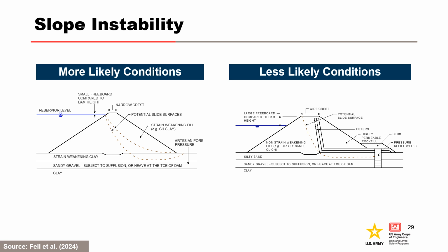The fourth and final internal erosion breach mechanism is slope instability. Internal erosion could cause high pore pressures in the foundation or embankment, resulting in reduced shear strength and slope failure. Breach could occur if the failure surface or progressive instability without intervention intersects the water surface, or slope deformations are significant enough that the remnant slope cannot resist water load.